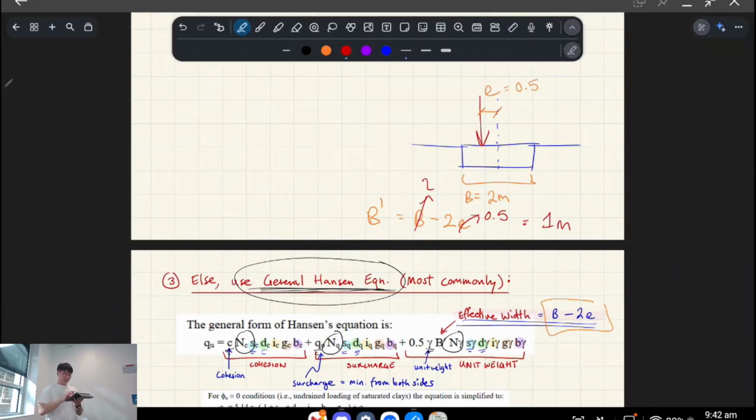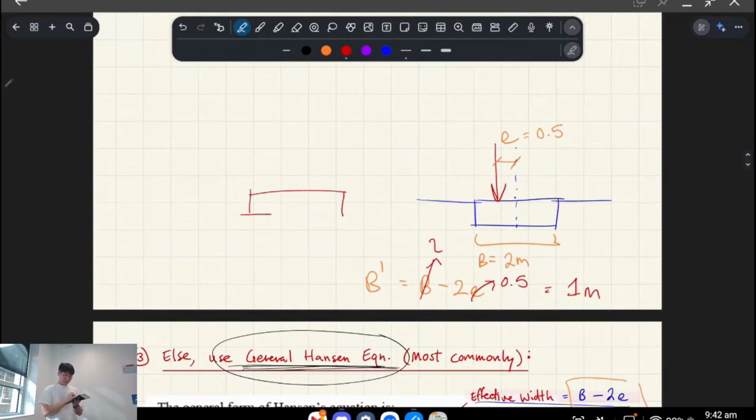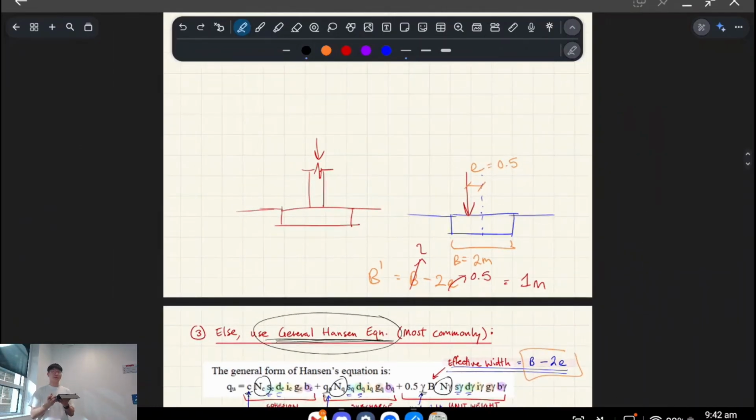Basically, if you have a concentrically loaded column, that utilizes the majority of the pad, right? But as soon as you have eccentricity, or the load is applied slightly offset from the middle, it's actually worse for your bearing capacity, okay? You generally want to avoid this unless you absolutely are forced to because of, say, architectural limitations, or you're at the boundary of your site and you need to have the column in a certain spot. Okay. Any questions about that?